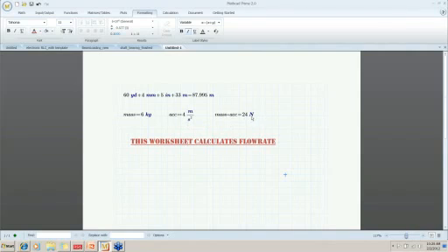Now, going back to the units, newtons, meters per second squared, kilograms. Up here on the formatting tab, we talked about formatting text on the left-hand side. On the right-hand side, we have a little drop-down window, and you can see here variable is what's selected right now. If I click on this drop-down, you'll see we can apply formatting to variables, units, constants, functions, system words, and keywords. So everything in this drop-down can have a different format.